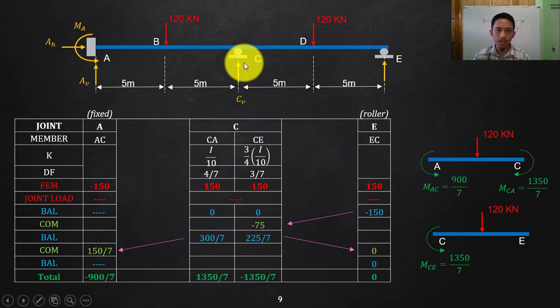If that is a joint which is not supported by a fixed support, the summation of the end moments there should be 0, which is in our case correct. That is how you will check. That should originally be 0 since there is no fixed support or moment here, so nothing will be counteracting that one. So we are correct. Another way of checking.